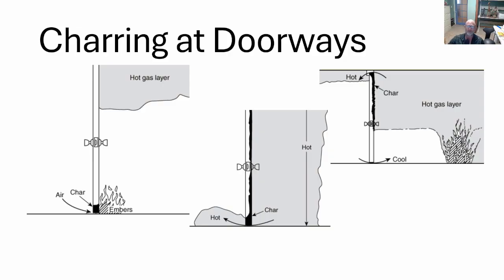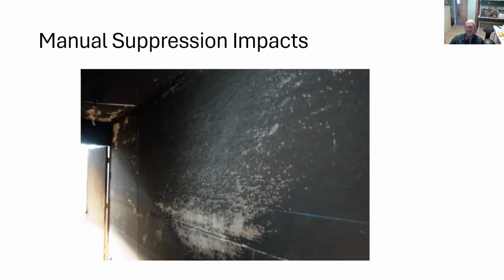There are variables in terms of how long the fire is going, pressure differentials, things like that. That's going to result in greater ventilation. But the real takeaway is if you have adequate heat, and you have ventilation affecting that localized region of heat, you're going to have greater char depth. Use this to your advantage in diagnosing areas of potential where fire moved to or originated from.